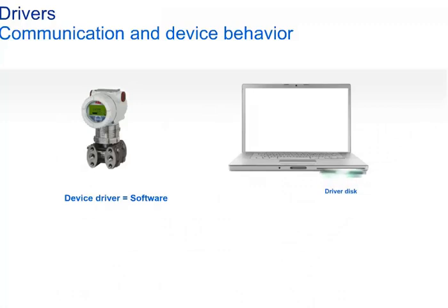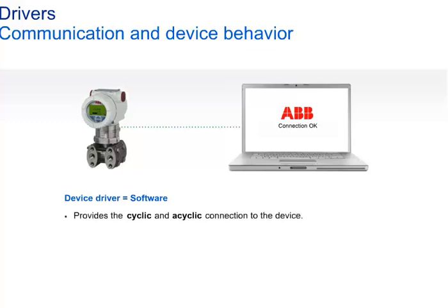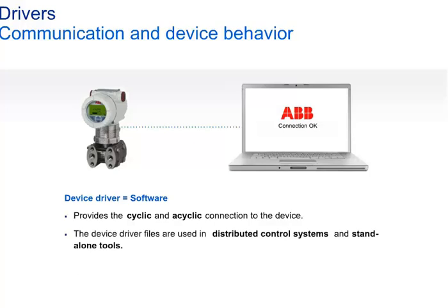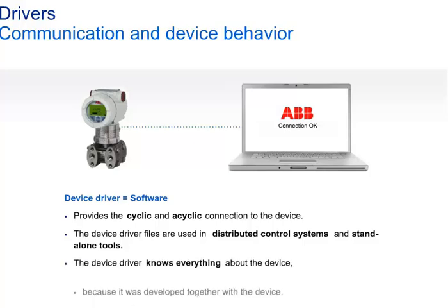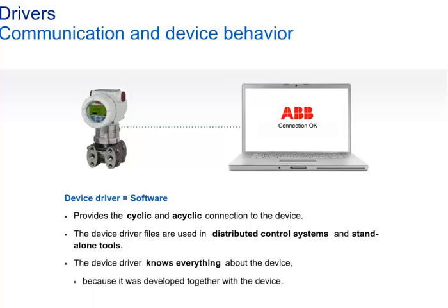So, what is a field device driver? Well, basically, this is a software module that describes the external interface, the communication, and the internal parameter world logic, the behavior of every single field device. It's this driver that allows for cyclic and acyclic communication between the field devices and the tools and systems. Device driver files are used in both distributed control systems and standalone tools. As the device driver is developed together with the field devices, it just knows everything about them.